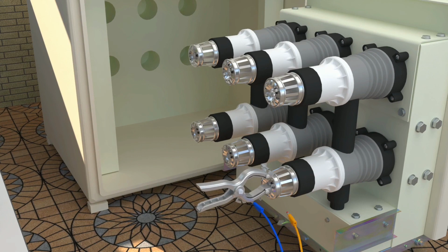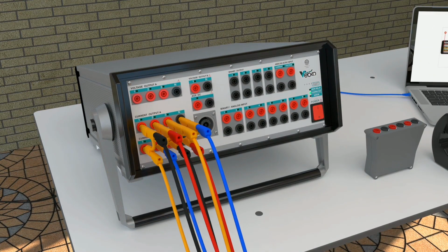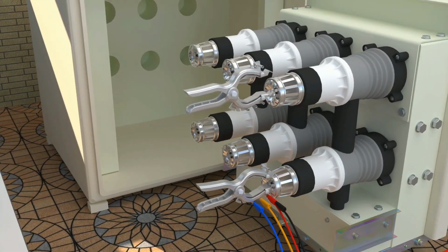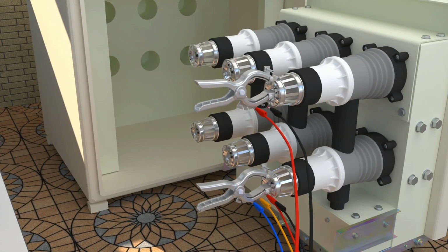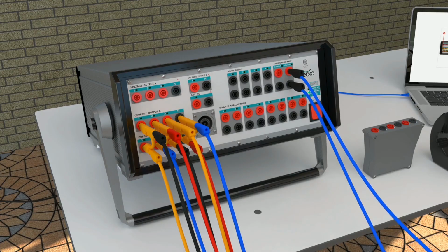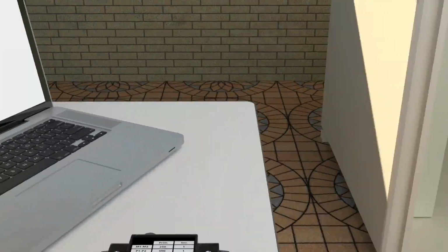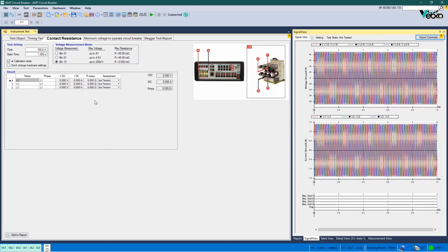To measure the voltage, the selected binary inputs should be connected to the CB contact and further from the current connectors. Note that to perform the test using a clamp and injecting high currents, multiple parallel wires should be used and they should be connected to the side where there are 3 pins, while the voltage measuring wire should be connected to the side where there is only 1 pin. To perform the test, right-click on the phase related to that row and select Apply Test.